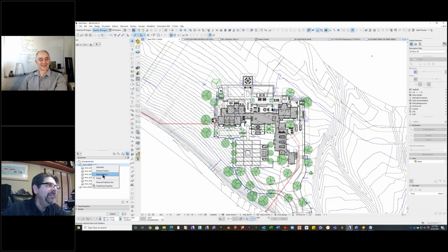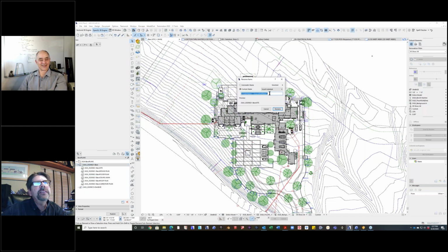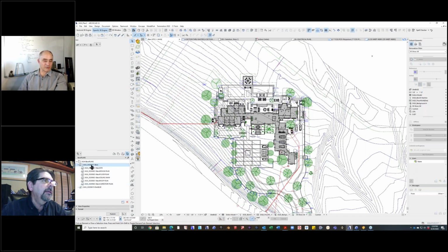So when you do your name items, rename item, you can put in hot text here. It's like auto text anywhere else. And so that's source ID and source name. So because my source ID comes from the folder, by changing the date in the folder, I change all the dates on the files themselves. Okay, so then you have a suffix, which would be design plan, floor plan, or ceiling main. Those are put in after that. So when you change the folder name, all of those change.